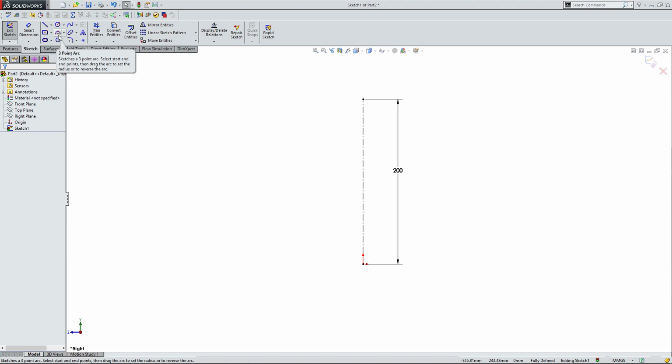Now there are a few different options. You can either create it using arcs, since the bottle is going to have a little bit of an organic shape. It will likely be created using lines, arcs, and possibly even splines. Now the problem with splines is that if you create a manufacturing drawing, now I'm looking a little bit ahead, creating a spline might be a little bit complicated because it may be hard or confusing to dimension the complicated arc itself.